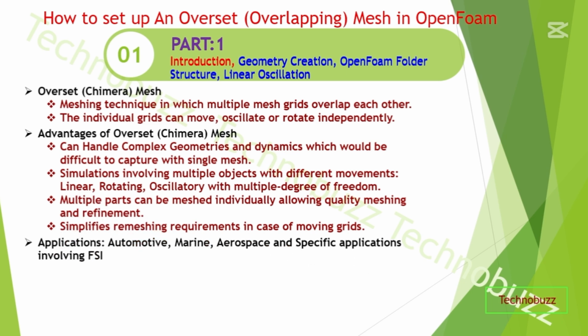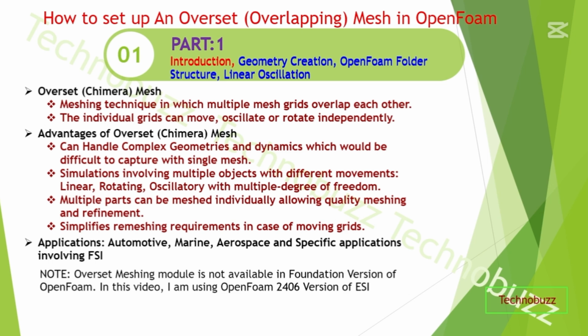Applications. This technique would be handy in dealing with multi-body dynamics in areas such as automotive, marine, aerospace, and specific applications involving fluid structure interactions. It may be further noted here that the overset meshing module is not available in the foundation version of OpenFoam.